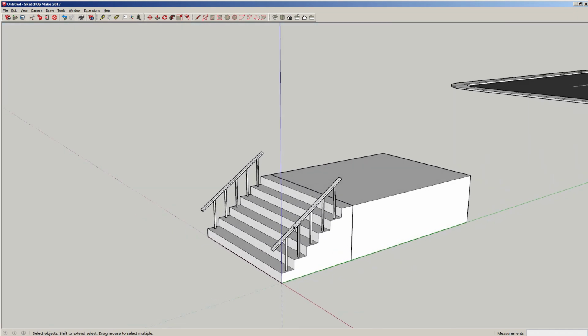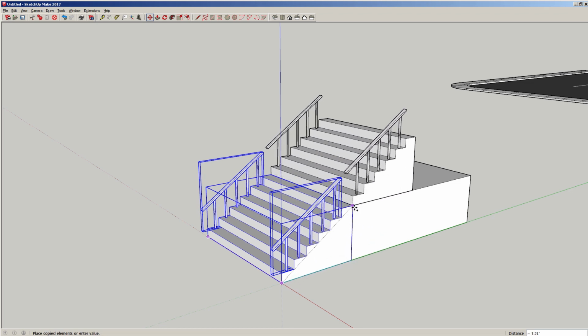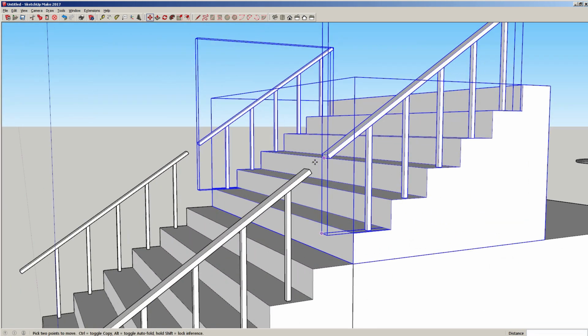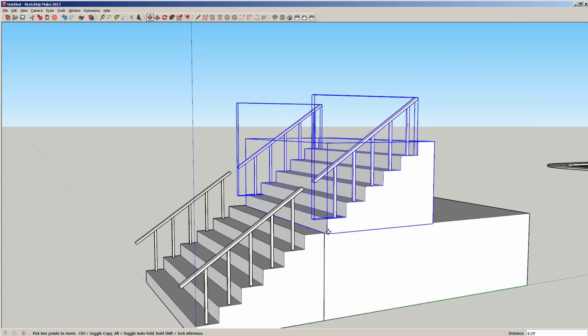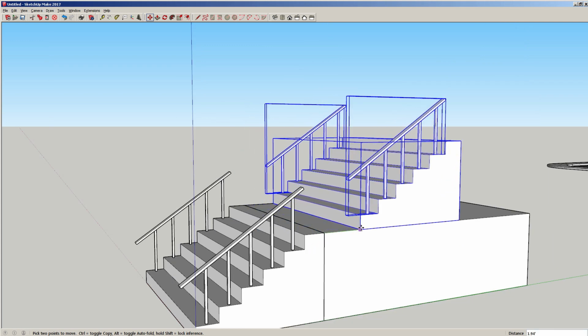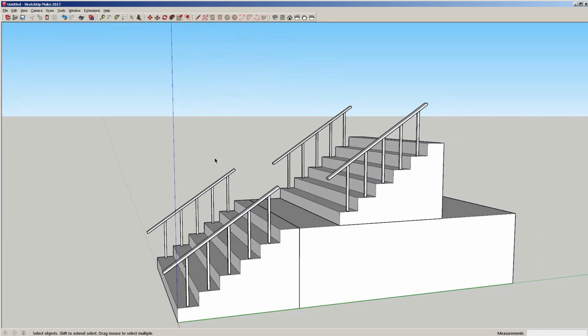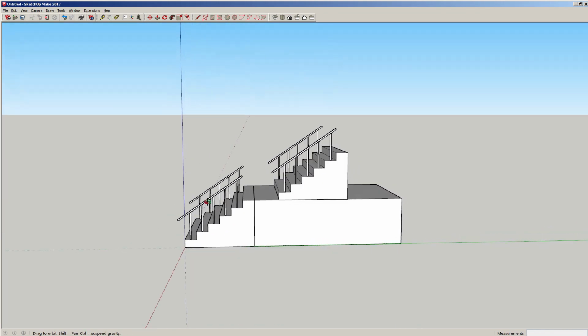And then what if you want to do a double stair set? Well, let's select all 3 by holding shift. Press M. Click on the very bottom corner. Press Control. Release both Control and the mouse. And there you go. But notice that the rail doesn't align. That's fine. We can press and pull to connect it, but wait a second. What if I want a gap? I have a double set. Of course, this is 8 feet high, but you get the idea.